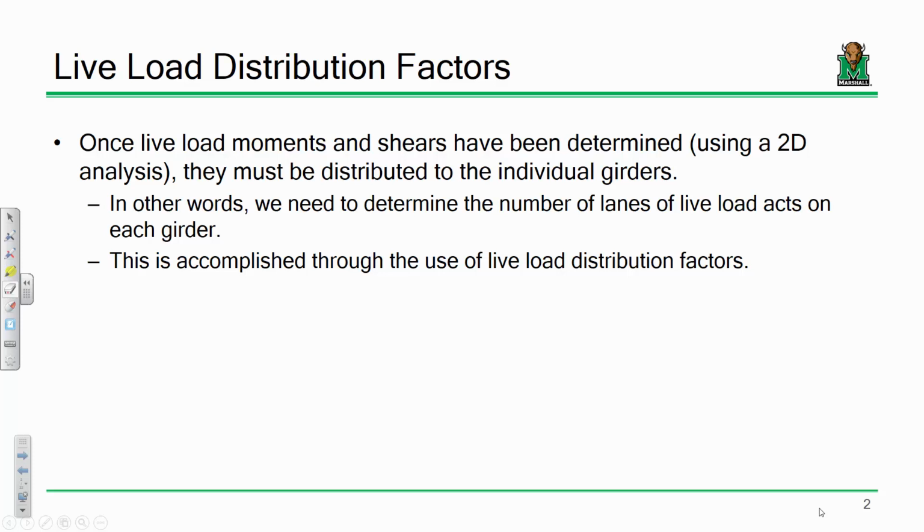See, the purpose of a live load distribution factor is to take a three-dimensional problem and collapse it into a two-dimensional analysis. Again, a bridge is a three-dimensional system. If we can collapse it into two dimensions, that's what we want. Because every civil engineer learns structural analysis in college, and uses it throughout their career, in a two-dimensional setting. A shear and moment diagram is a two-dimensional problem. You have an x and y axis, and here's your shear and moments. We love 2D analysis, because it's easy to perform. We can do it any day of the week.